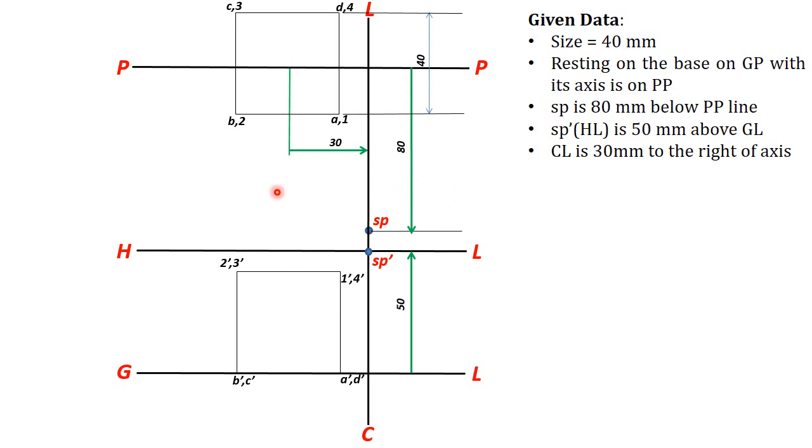Now to find the perspective view of these 4 points, you should extend the visual rays up to PP. That is our procedure for visual rays. The top view visual ray should meet PP, because these points are in front of PP and normally it won't meet, so you should extend it up to PP.